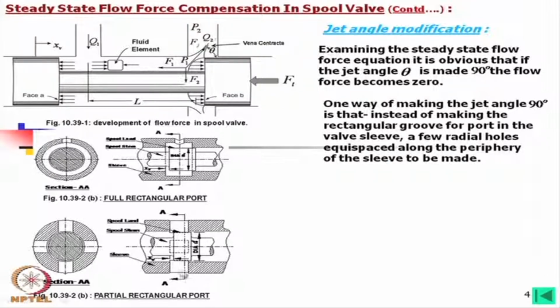One is non-conventional machining, electro discharge machining or something can be used, but for mass scale obviously it can be done with the use of broaching. How is it done? First we make a circular hole by drilling. Say if it is 90 degree, just 2 cross holes we can provide there, and then using a broaching tool we can make this square hole.